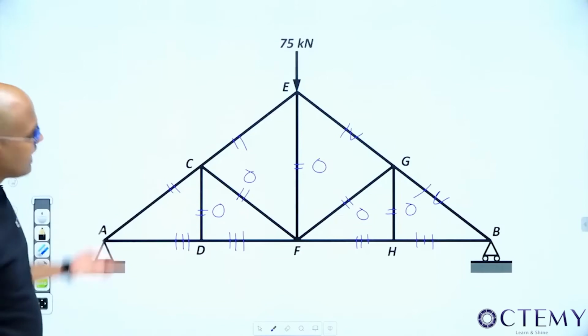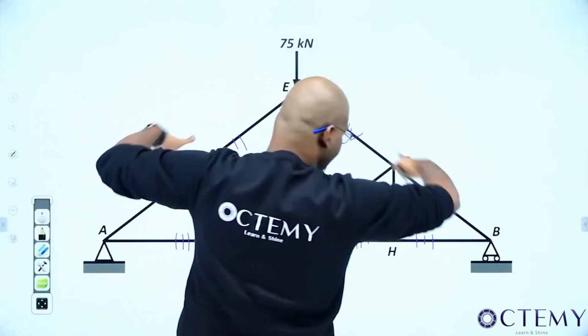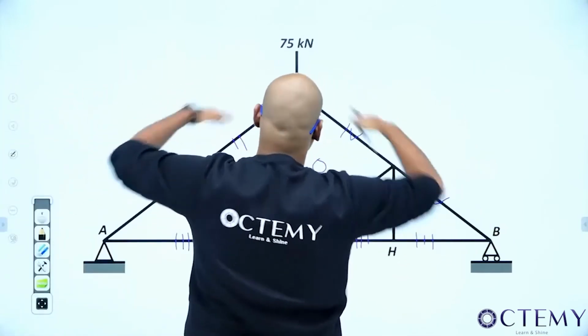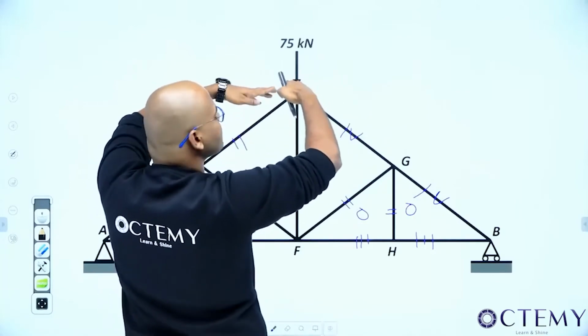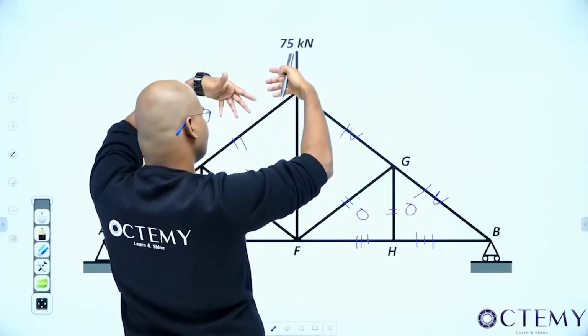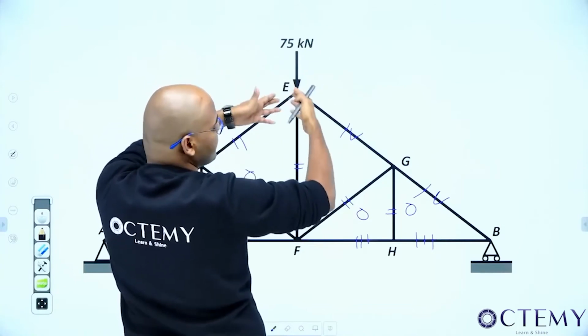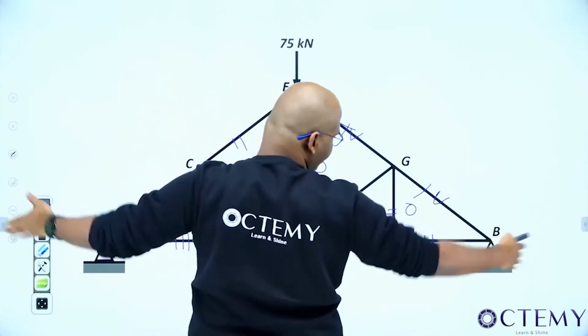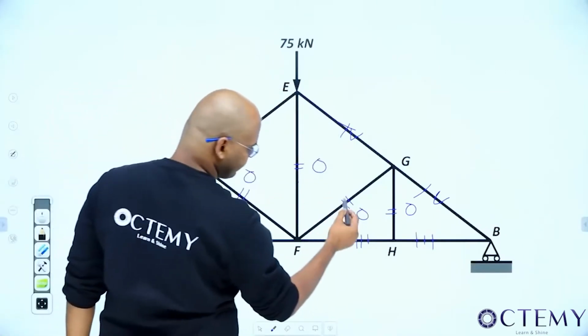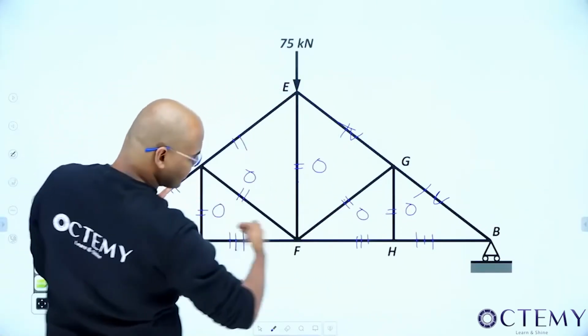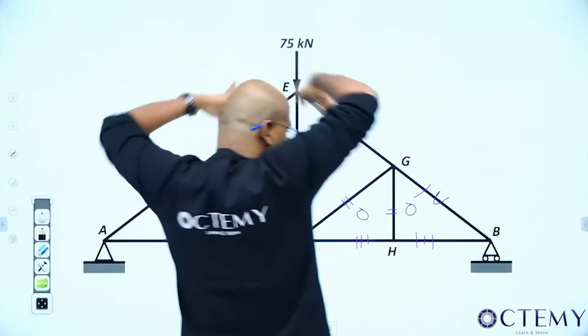Are you okay? And as it is symmetrical, even these members will share the same load. You just find out here. Apply the coplanar, system of coplanar concurrent force system. You can resolve the two forces and equate them. You'll get equal magnitude being transferred. Okay. So how many members in total? 1, 2, 3, 4, 5. Complete the inside, whatever is there, there will be 0. Load will get transmitted like this.